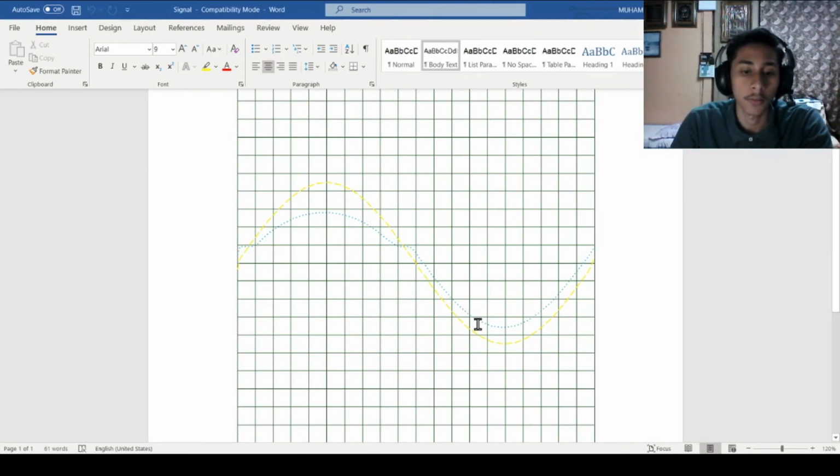Now for the graph from the simulation oscilloscope, the yellow curve is our input signal, while the blue curve is the output signal. The output signal follows the input signal perfectly within the same phase. The output signal is shown to have a lower amplitude compared to the input signal. This is due to the loss from the transistor, which has a gain AV under 1.